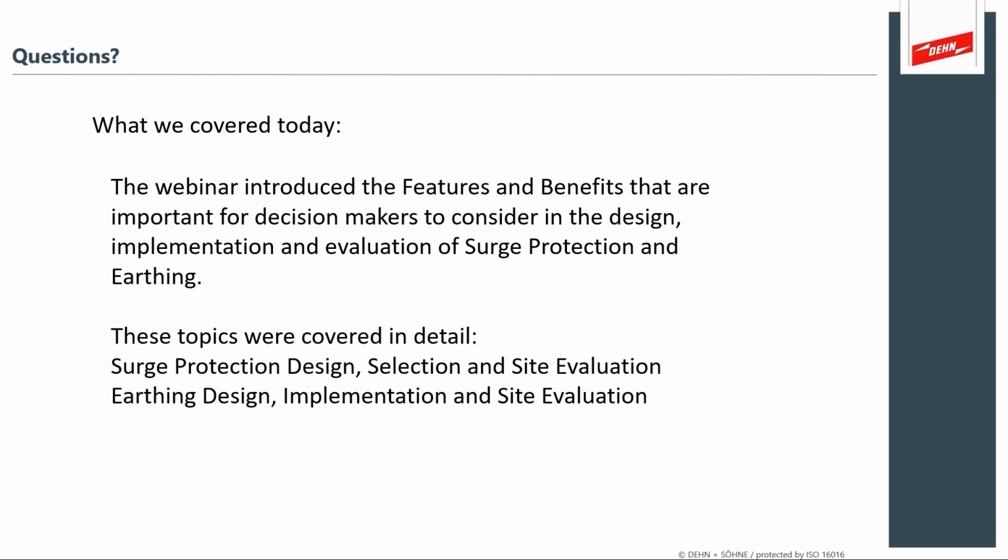I would just like to address this last question, addressing maintenance on SPDs. The person is asking, what type of maintenance schedule should he put in place for the surge protection devices he has installed? So SPDs generally do not last forever. Metal oxide varistors do degrade over time, and it's sort of a double question. How often are you being struck by lightning? How often are you experiencing problems on your site?